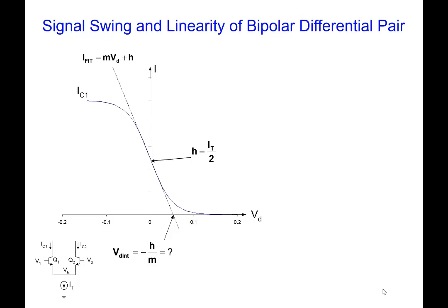How do I get M from the graph, or the analytical expressions? From the graph, first of all, what is M? It's the slope of the tangent line, right? Yeah. So I just need to find the tangent line at VD equals 0. So it's the partial of IC with respect to VD, evaluated at the Q point. Q point is where VD equals 0.